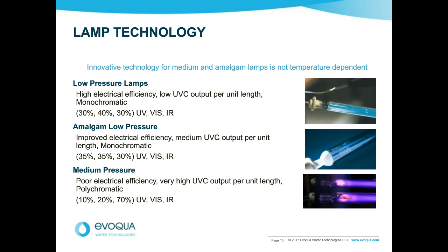Don't have poor hydraulics. Think about how the hydraulics are handled, and ask the UV provider to account for all of that. I think lamp technology will continue to be refined. I think that the lamp spacing is governed by the use of advanced CFD modeling. Computational fluid dynamics really is a very powerful tool to help us decide where to place lamps, how many lamps we need. You'll notice many of our designs don't have symmetric arrangements of lamps. The arrangements are asymmetric because we put the lamps where the water goes. The water isn't moving symmetrically through the structure, so the lamps shouldn't be symmetrically placed. So we have a variety of emulation tools. We have a lot of validated machines, so we know it's our job as manufacturers to be intimate with how these machines perform. And when we're asked to make performance guarantees, then we can, because we understand how they perform.